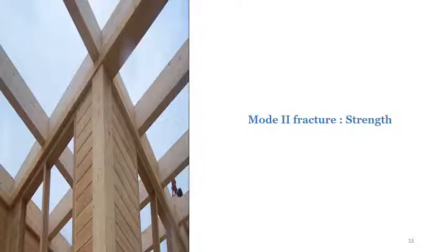In order to analyze the fracture behavior of fibrous materials such as solid wood, it is important to determine the fracture mechanics properties, such as the energy release rate and the stress intensity factor, of the different fracture modes. The in-plane shear mode 2 is indeed one of the modes that cause the collapse of the wood structure. In what follows, we will explain the different stages of the tests carried out.